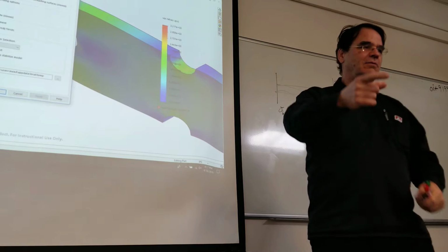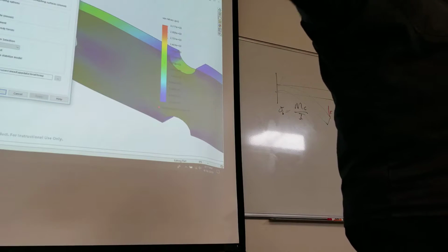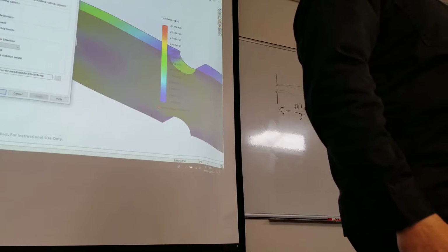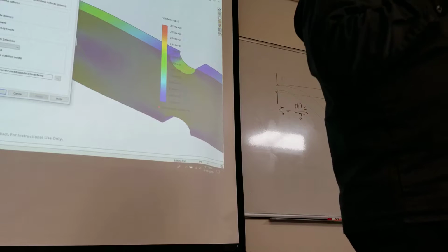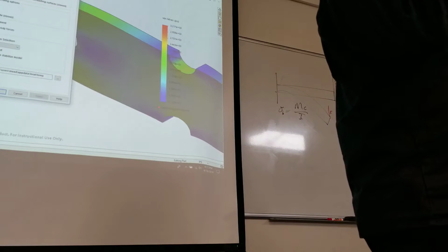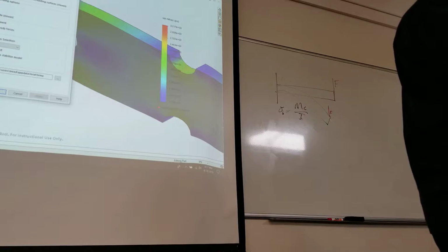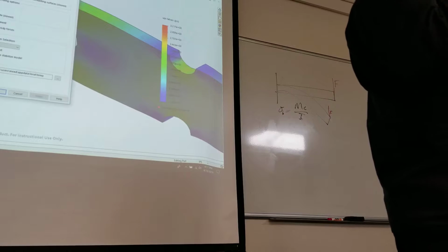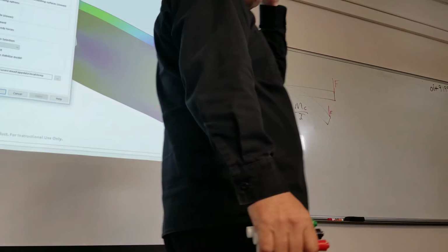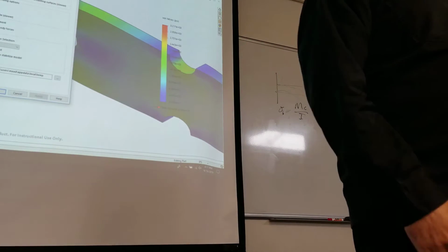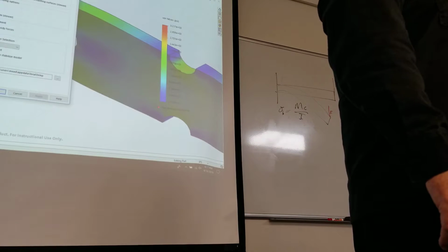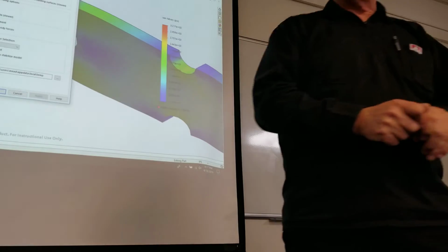And so now instead of going through these once, we're going through them multiple times, iterating through them until they converge. It's going to go through it at least twice, always, because otherwise it doesn't know it's converged. The only way it knows it's converged is it runs it once and then runs it a second time and the answer doesn't change very much. That's the only way it knows it's done anything. So the instant you put a large displacement flag on this, it's going to run the analysis at least twice. And that assumes that it converges. It may run it more than that. So it's going to slow you down quite a bit, even on some of these faster analyses.